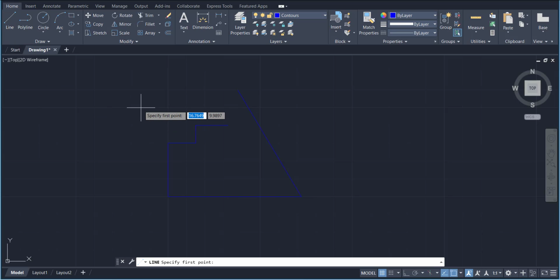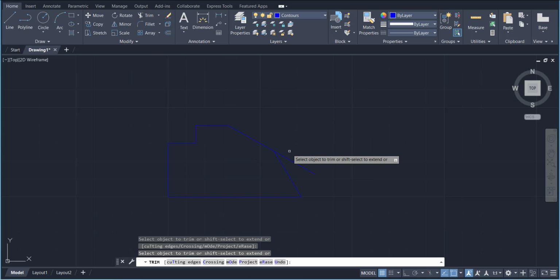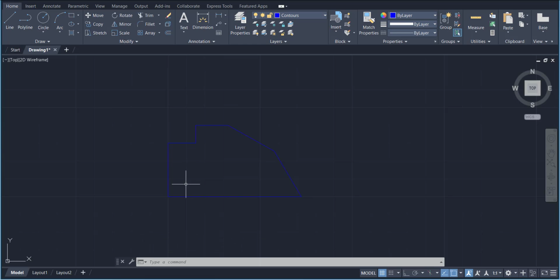Okay, again a line, and this line is starting from this point, and again we need a line at an angle. So make sure this line passes this line at this point, then press tab, and this dimension is given as 30. And now trim, and we have to trim all of these lines like that. Now according to our drawing, at this point we also have hidden lines. Right now I am not going to draw the hidden line.